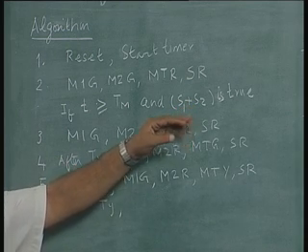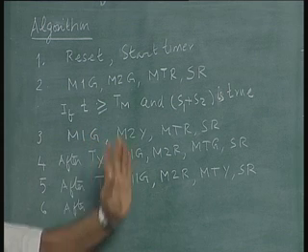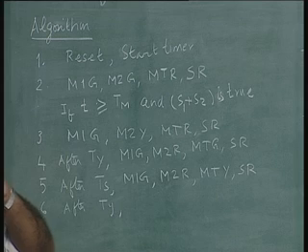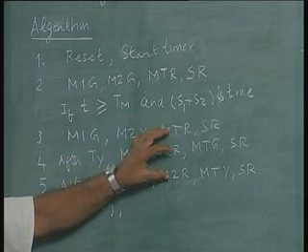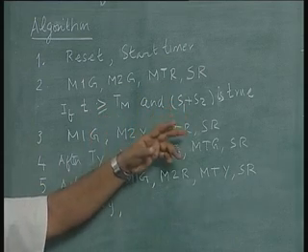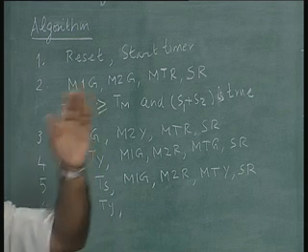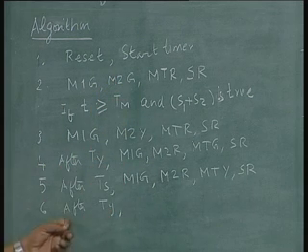So, we do not have to spend time to give the green signal for turning from the side road to the main road, we can return to the main sequence. On the other hand, if S2 happens to be 1, either because of that or because both S1 and S2 were on, we would like to service the side road turning into the main road before we return to the main loop. So, that has to be tested here.